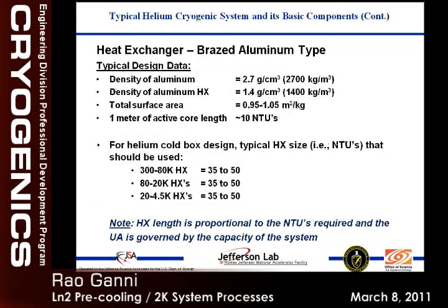Yeah, these are some of the things. If you look at it, like I said, 73% of the duty is done by one third of the heat exchanger in length. From 80 to 20K is another third, and 20 to 4K the rest. So give or take, that's how the lengths of these stacks vary.